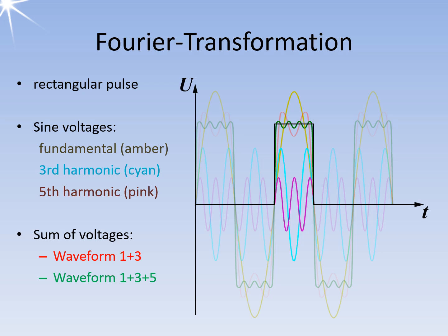However, an increase in bandwidth also leads to a higher noise level entering the receiver. Since white noise is distributed independently of frequency, it follows that the broader the frequency range to which the receiver's bandpass filters are tuned, the higher the noise level will be. This results in a lower signal-to-noise ratio and, consequently, decreased sensitivity of the receiver. Therefore, a compromise must be reached.